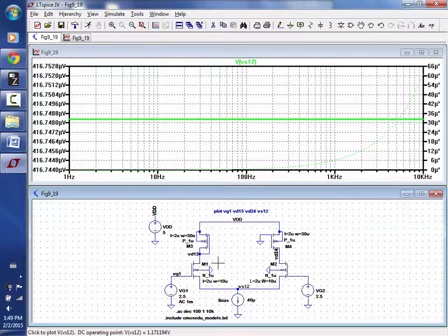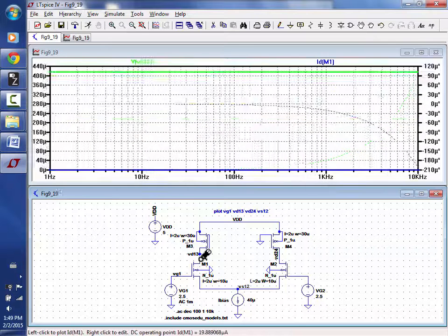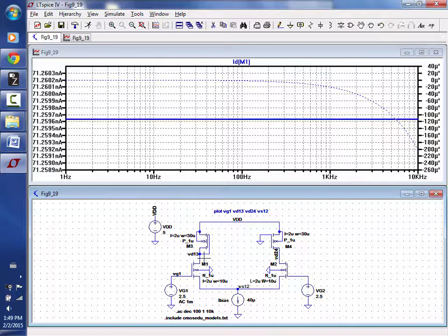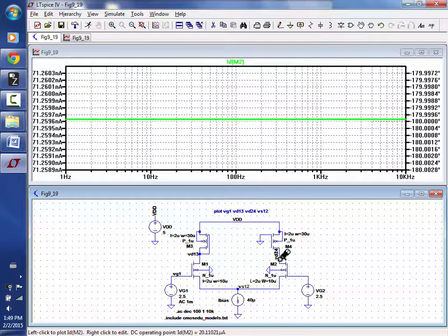Okay. AC current flowing in here, 75 nanoamps. It says 71. My transconductance is off a little bit. 71. And if I do the dot OP again and look at my GM, I'm going to see that it's slightly less than, I keep saying that, the body effect.